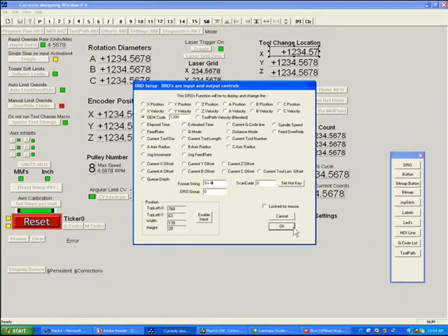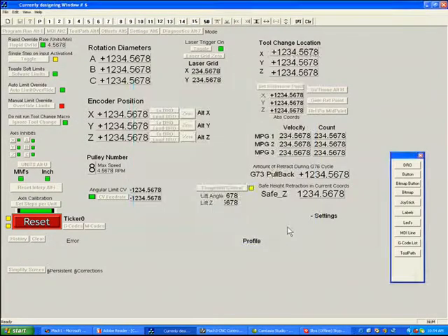In CNC, you normally would want 4 places of resolution after your decimal point. I should note that the program really doesn't care how you display it. It will always use up to 12 to 15 decimal points for accuracy. But these are display issues, and most people want that warm and fuzzy feeling they get from seeing the full 4 decimal places in any number.